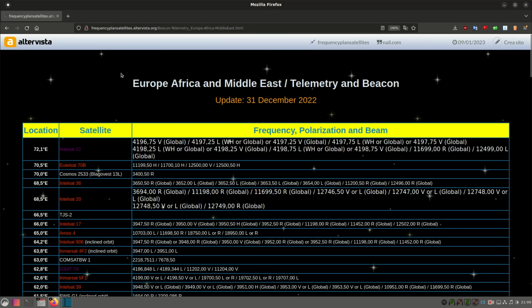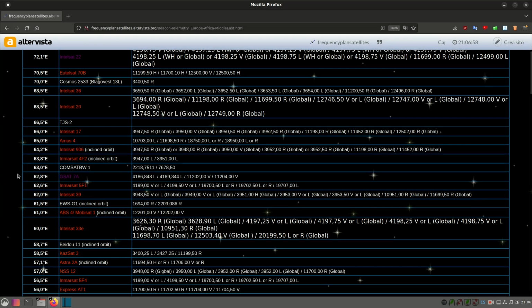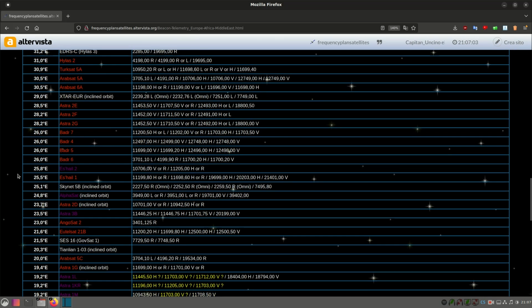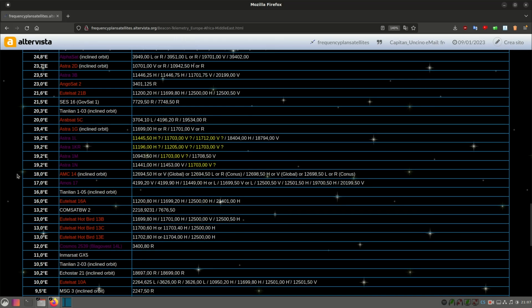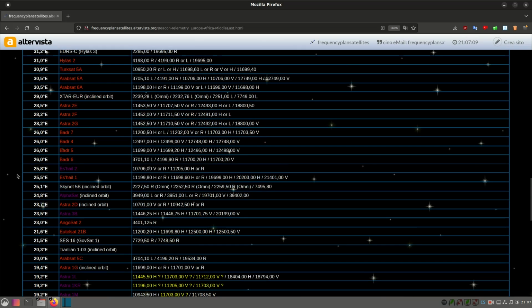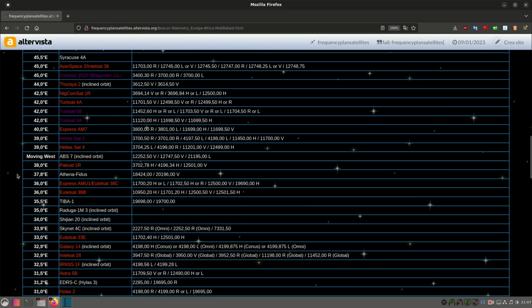But if you don't want to be searching blindly, you can go to a website which lists TV satellite beacon frequencies. These beacons are different from the standard data transponders, as they are usually very narrow and very strong, low-rate data streams with a carrier in the center. The beacons are scattered all across the Ku band, though there do appear to be some portions of the band where they are more common.